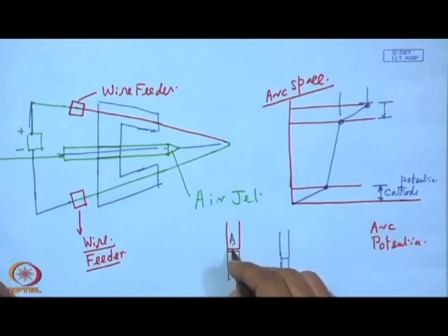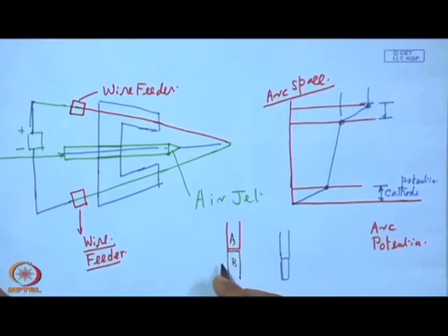So, when they are in intimate contact, there is no arcing, but when we try to separate them, the reason is as follows. When you try to separate them, the number of contact points gets reduced, and as a result current density in those high points of asperities will be more, and that will cause localized generation of heat and temperature.